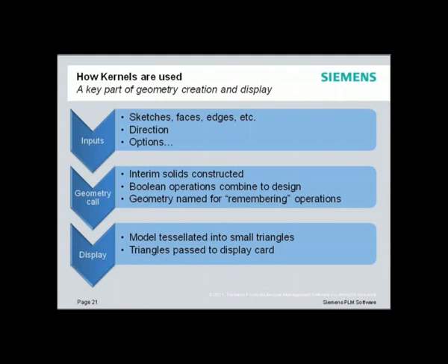So much so that, in fact, and I'm sure SolidWorks does this also, we version our algorithms. So if we were to improve an algorithm on how you do a round in a certain situation, we would, in fact, version that so that your existing files would always use the old math to compute it, so you can be guaranteed to get the same solid at the back end.